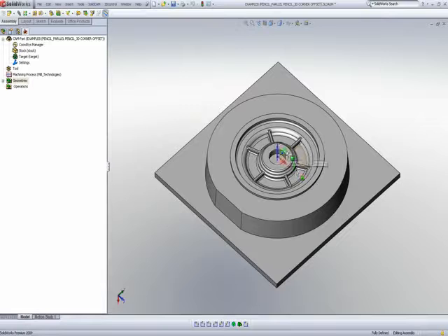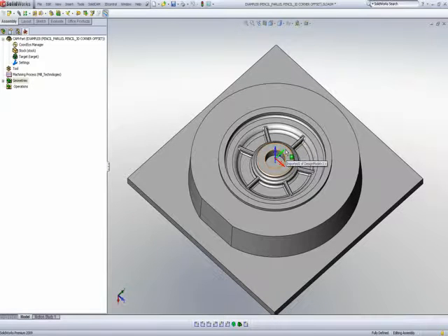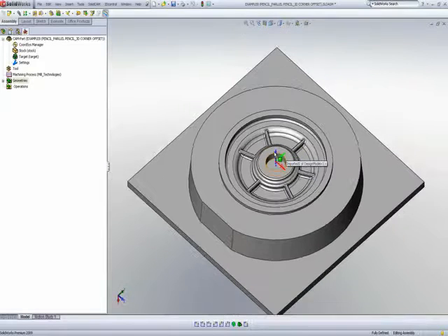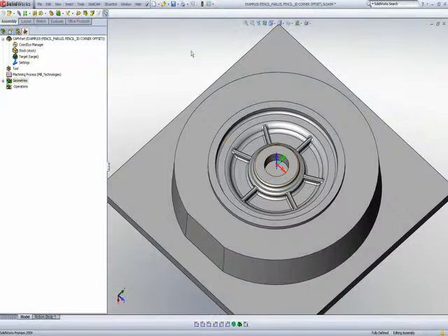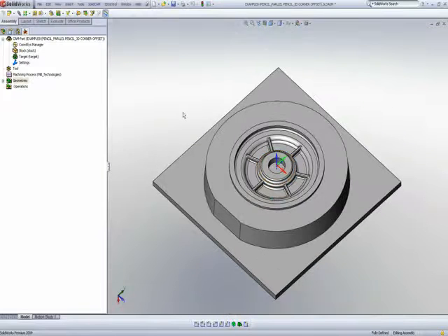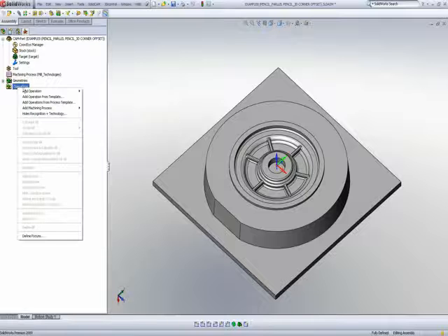We'll first start off on this part using pencil machining. What pencil machining does is that it picks up every single one of these corners over here and does a pass on every single one of those corners, and we'll show you exactly how this is done within the operation.